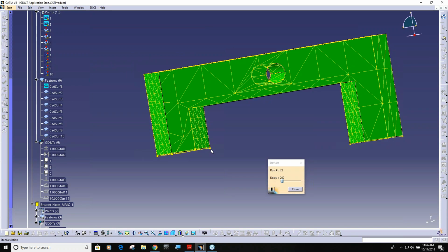As I always tell everybody, our software is point-based and feature-based. This is my example of trying to show you. So when I do my modeling, I try to stay all feature-based first. If I can't simulate what I want, then I will go to feature points. If I still can't simulate what I want, then I will go to coordinate points.